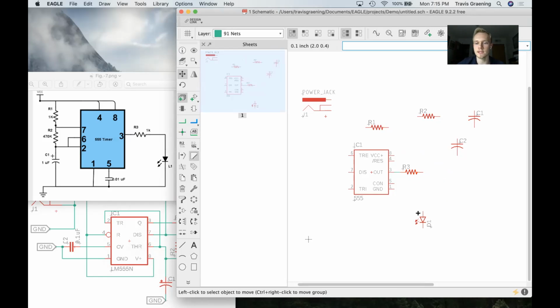And then that, as we can see, is connected to our diode. I'm not going to connect it exactly as seen in the schematic. I'm actually going to rotate it around a little bit and have it pointing this direction. Now, to connect those parts manually, I'll just go over to my net icon right here, hover over one of the connections, drag it across and click on the other green circle right there. And we've made our connection. So hopefully that's going smoothly for everybody.